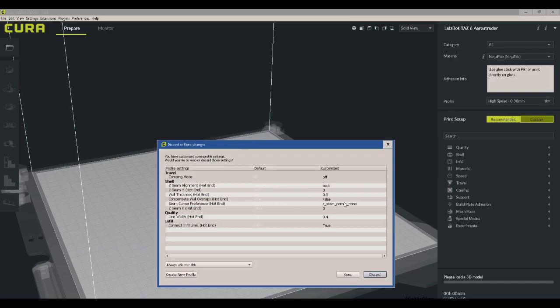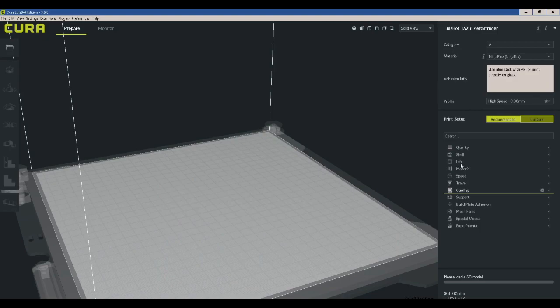and then we have wall thickness, which is modified to match the thickness of my nozzle. We'll change that because we're going to be changing our line widths for TPU just from experience. So there's just a little snapshot of everything that I had modified on that Polylight PLA high-speed profile, and I was getting really good results with it. So we'll go ahead and keep those for now.